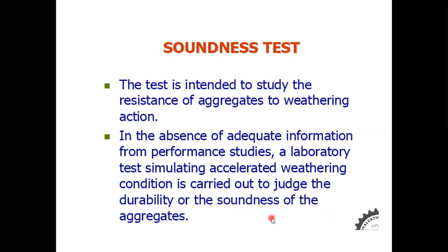So how will you test weathering action? It takes a long time, but how to conduct it in the laboratory? See, what we are going to do is accelerate the weathering condition, the effect, like using some acids, some chemicals, and you will try to see how the aggregates are going to resist these chemicals.